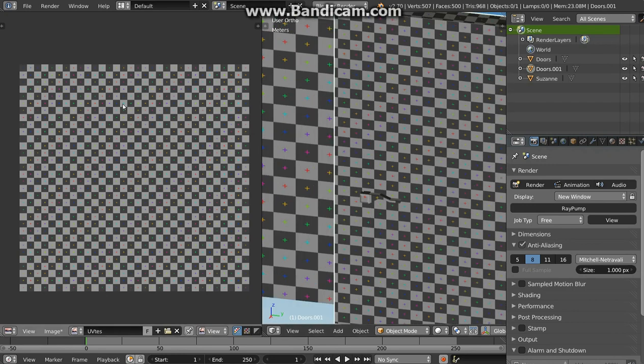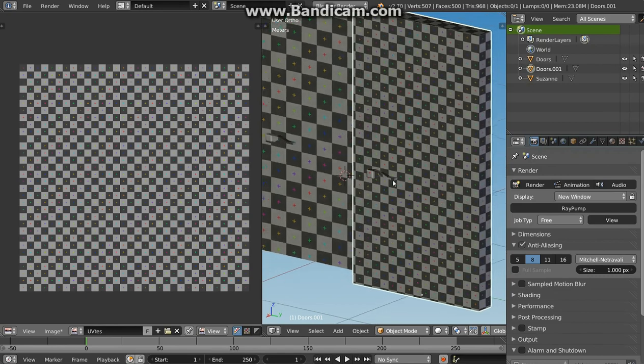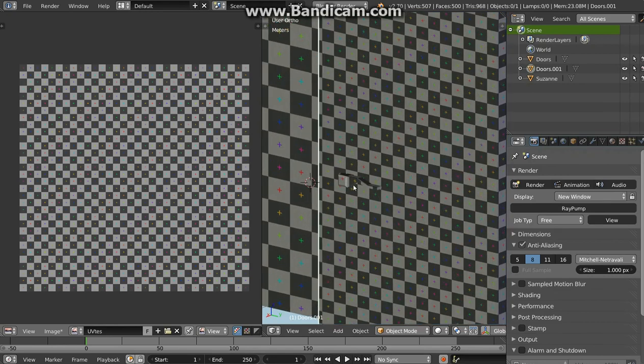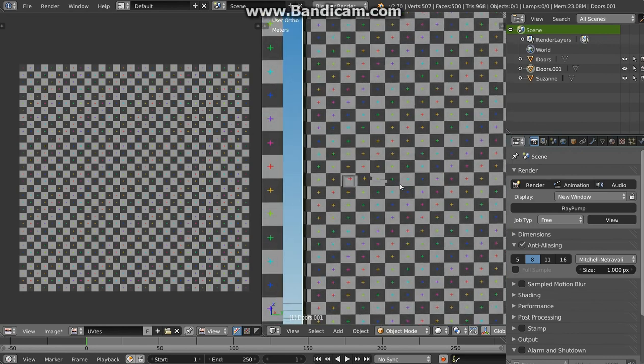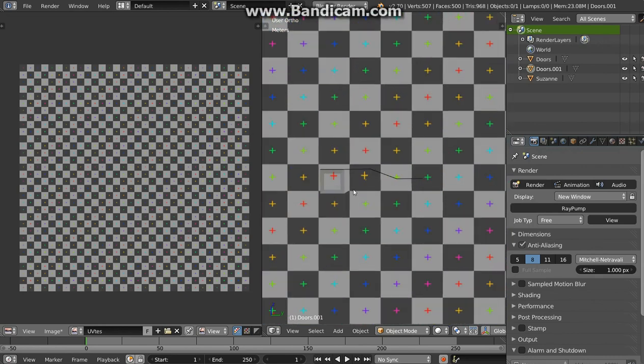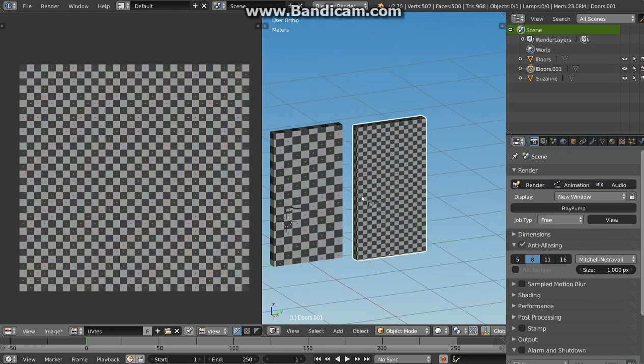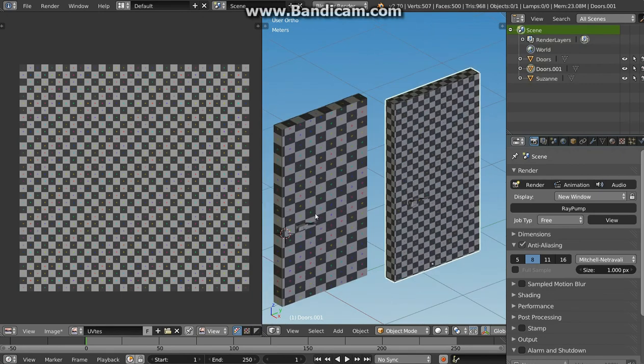This is why for the UV unwrapping you should always use this texture, or similar ones with little circles or just predefined geometrical shapes and colors. So you will see where your texture is, if it's stretched or deformed somehow, and most importantly that the squares are the same size throughout your whole object and through all the objects in the scene.